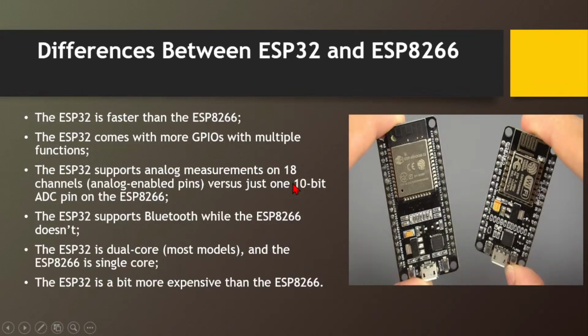So this you can see, this is an ESP32 board. How does it look like? There are two types of board generally, one is ESP32 and one is ESP8266. When you go to buy this ESP32 board, it's generally called Node MCU as well. When you go to a store, just tell them that you need ESP32. I have seen students get confused because they look very similar and they get the ESP8266 module.